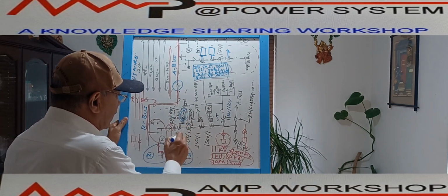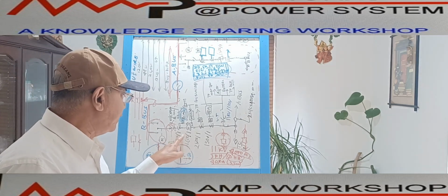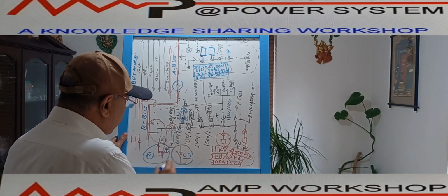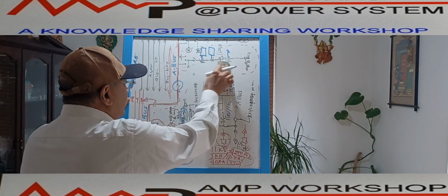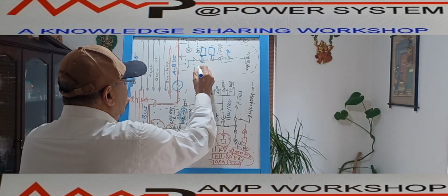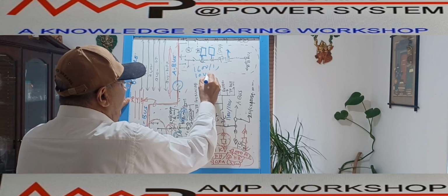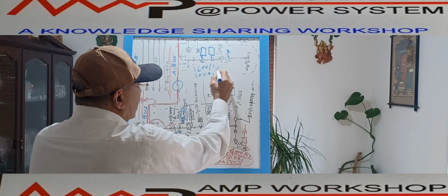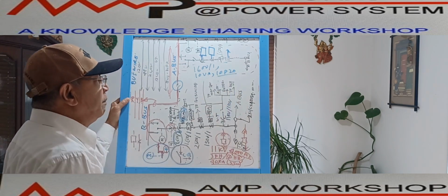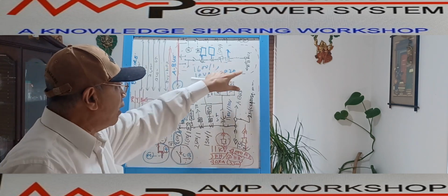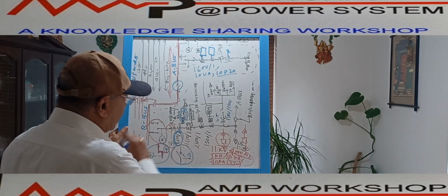For this box there is a CT. That CT ratio is 1600/1. We are considering a 1 ampere CT. It has some VA rating. So when we write the rating here, we have to write it this way. First we write the ratio, 1600/1. Then suppose this CT is 10 VA, we write 10 VA. Suppose the protection class we need is 10P20, so we write the protection class of the CT as 10P20. These are the requirements for the normal protection relay CT. So those details will come here for this relay.